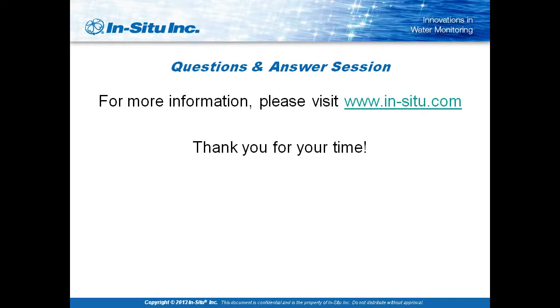Number two, you mentioned variable barometric influence on confined versus unconfined units. I'm reading this, so don't mind me. How does this change in bedrock versus alluvial aquifers? Okay. Just bear in mind that the barometric influence is going to be greater the more confined the aquifer. The less confined the aquifer, the more diffuse the influence, and hence the actual effect itself. So hopefully that answers that.